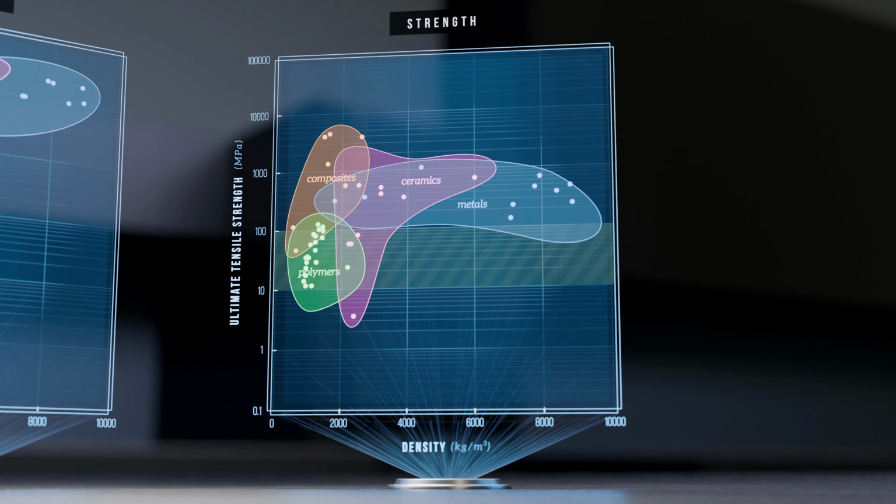One of the big advantages of polymers is their lightweight. Their low densities make them valuable in so many different applications, even if they might not have exceptional stiffness or strength. Some high-performance polymers, like polyether ether ketone and polyetherimide, which goes by the brand name Ultem, have ultimate strengths that are very respectable when considering their low densities.